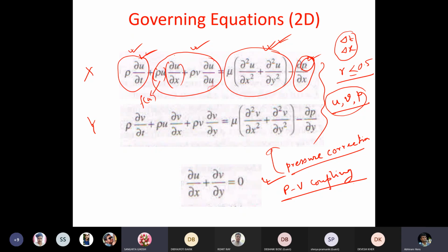So this pressure is basically normal pressure plus rho gh, which can be added here, and this is then called piezometric pressure. Piezometric pressure encompasses both the normal hydrodynamic pressure and the body force.